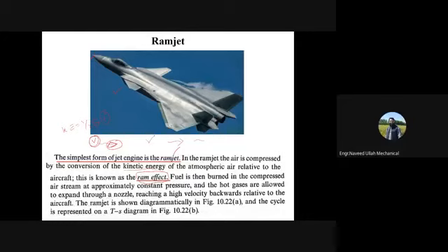तो the compression takes place but not conventionally, just because of the conversion of the kinetic energy or the velocity to pressure, and that is actually known as ram effect. Ram effect क्या है? Conversion of kinetic energy to pressure energy, that is known as ram effect. And this is important, इसलिए इसको हम ram jet कहते हैं, ठीक है।